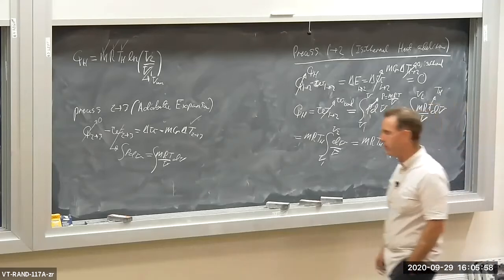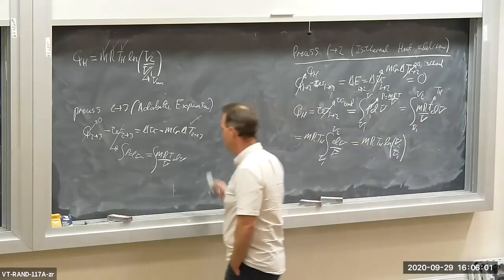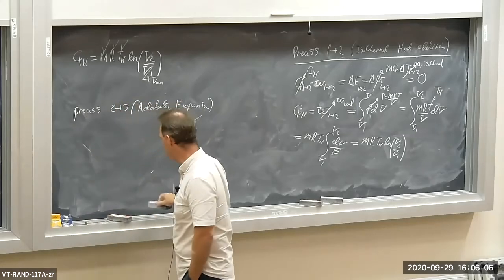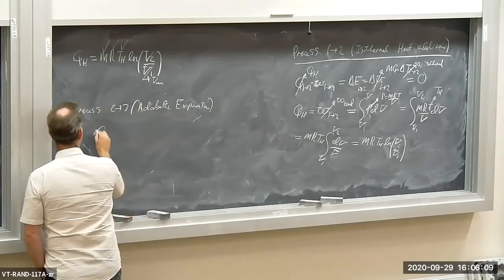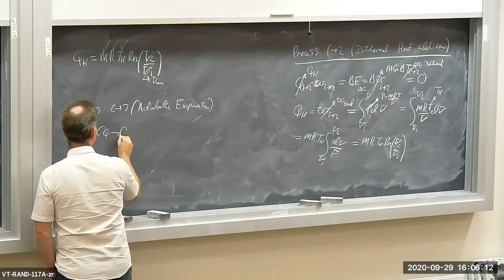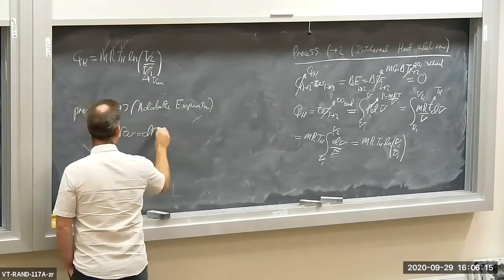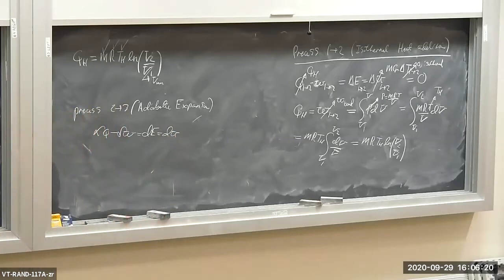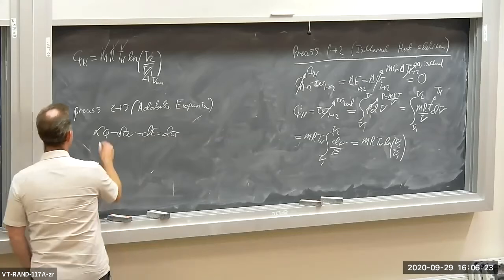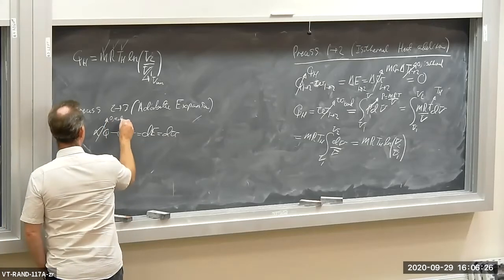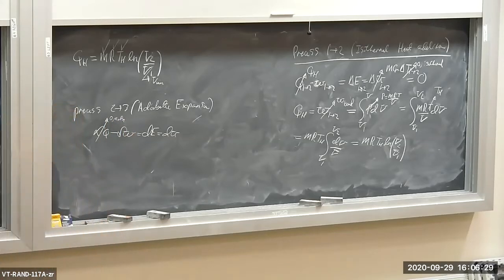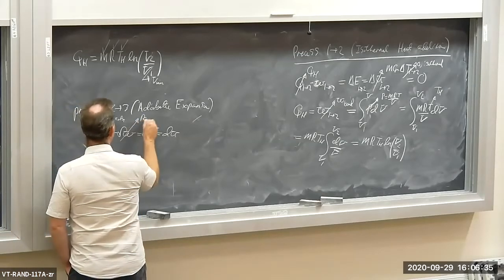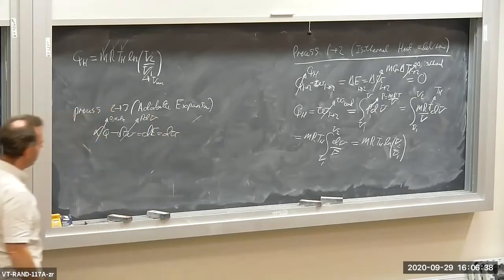We're going to write another version of the energy balance. I'm going to write the differential version of the energy balance, differential process. Del Q minus del W is equal to dE, which is equal to dU. Okay? That's a differential version of the energy balance. It's adiabatic, so that goes away. And of course, the work is boundary work. So this is P dV. That's the boundary work. Okay?